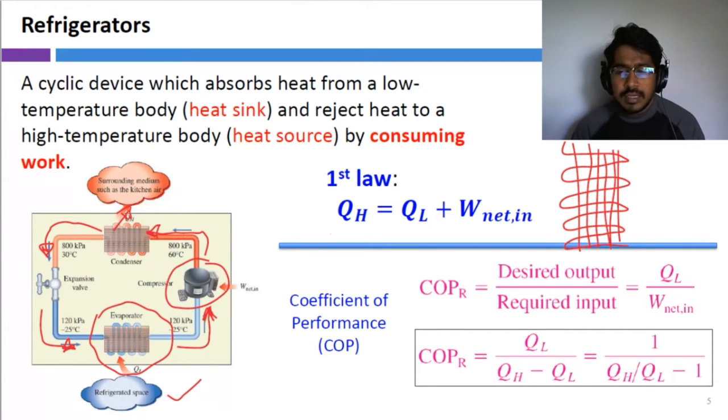That's the same idea, right? Even though we do not cover baseboards in our course, it's the same thing. Baseboards are used to heat your space. So if you just trap it, like if you put a couch around it, then the air cannot circulate. So it just heats up the local air, and it keeps doing that, but your space is not going to be heated as effectively. Eventually it will heat, but a lot of heat will be trapped behind your couch. That's why people say that you should not block the airflow to a baseboard, right?